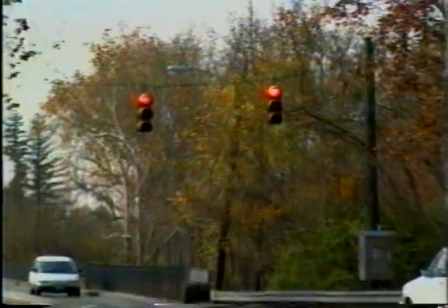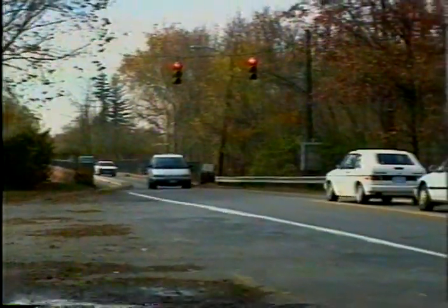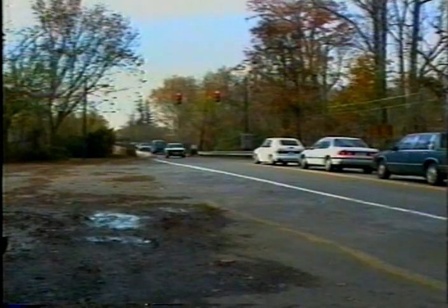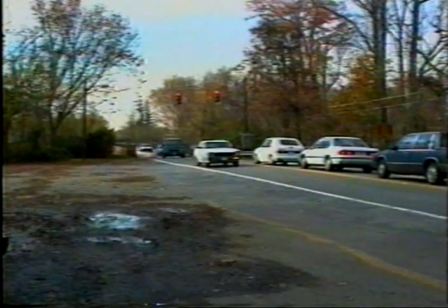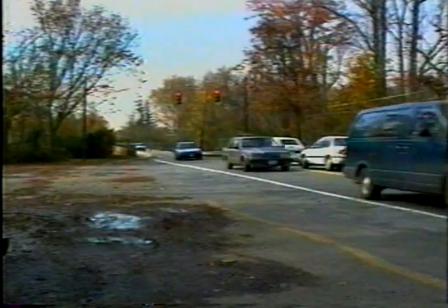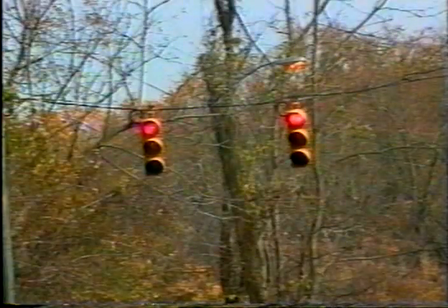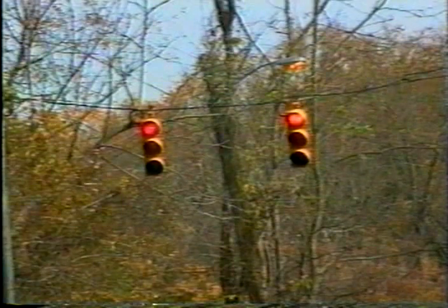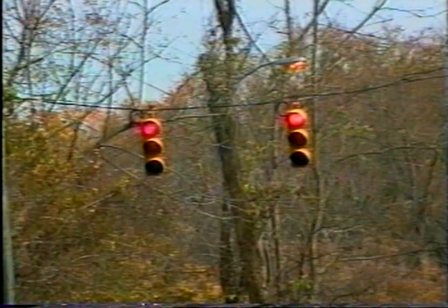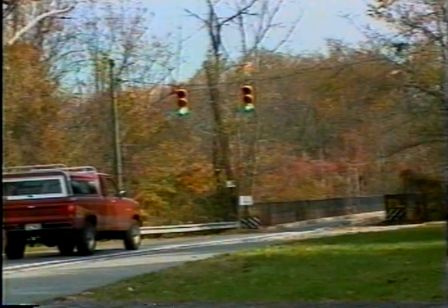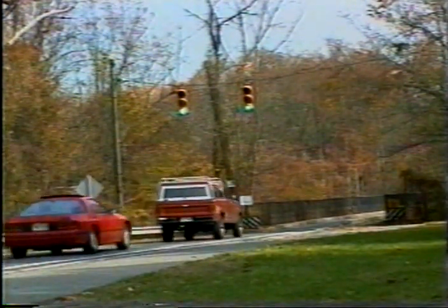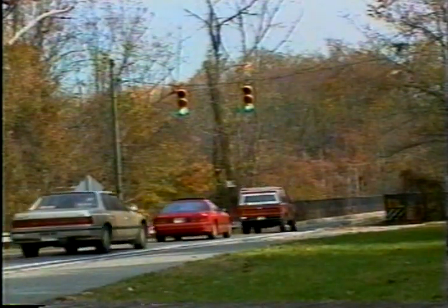Narrow bridge or tunnel signals are also standard traffic control signals. Their purpose is to control traffic through a narrow roadway section where two-way traffic would be unsafe. Two signal devices are used for each approach to the bridge or tunnel. One signal is at the left or over the left half of the roadway, and the other at the right or over the right half of the roadway.